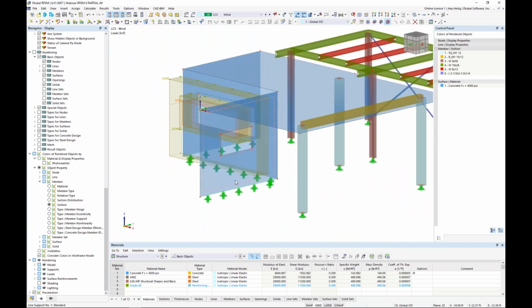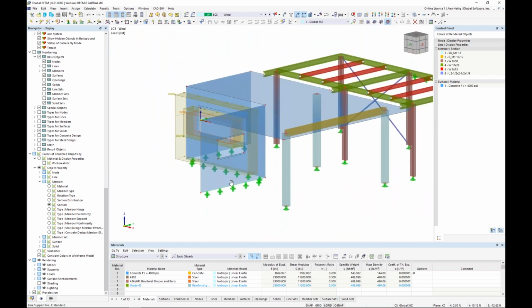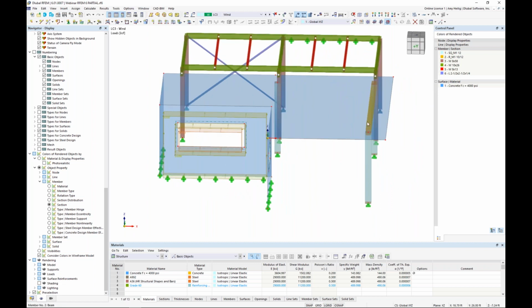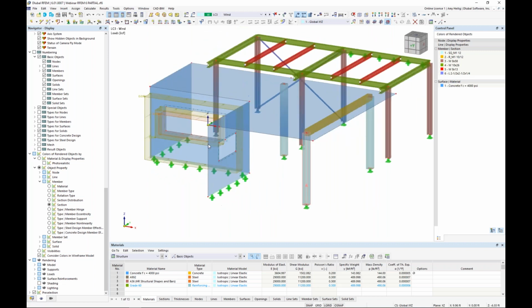In a similar fashion, let us consider that maybe in this entire open area here, we have some type of facade wall. And we didn't model the facade wall because it's not really contributing structurally to this particular model, but I'd like to consider it for wind loads. And I'd like to introduce you to a new feature that we've also added available under our surfaces option.